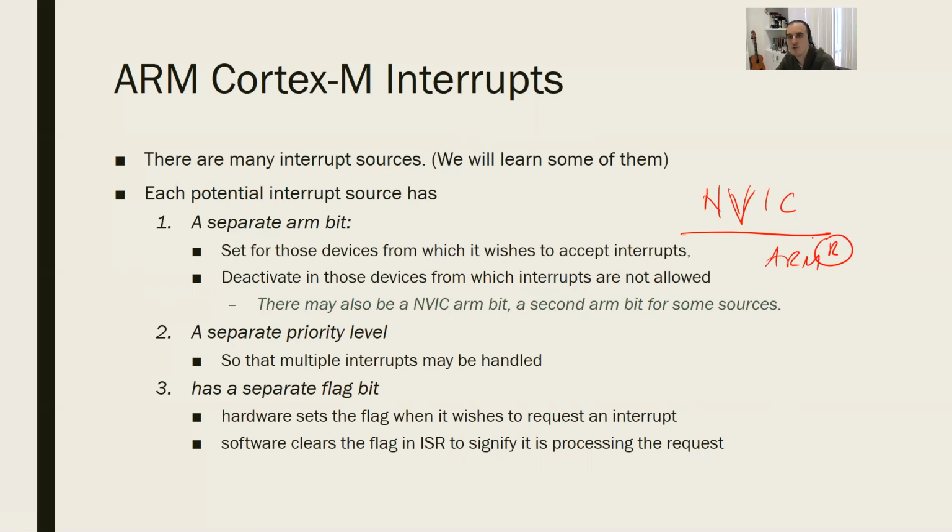Because if you used busy waits only, that would have been a terrible architecture. Imagine you're waiting for interrupts or triggers from multiple devices, and you want to design a busy wait architecture. While you're waiting for this one, the other hardware is maybe crying for help. It won't work. So when you are doing multitasking from multiple sources, you need a sophisticated interrupt architecture.